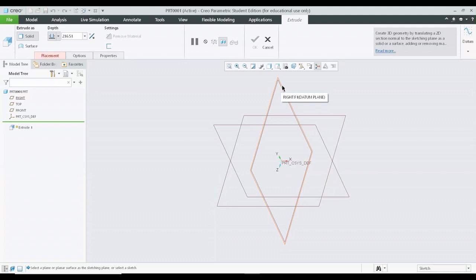For example, if we have a cylinder that is standing on the floor, in order to create the same object in the Creo software, the view of the object is more important. So in order to create the same geometry, I will choose the plane named top.